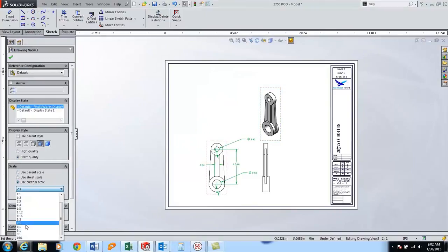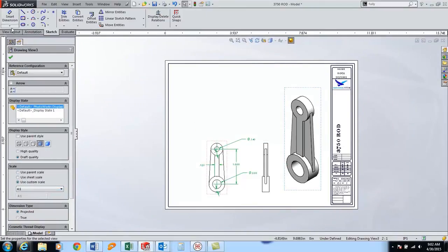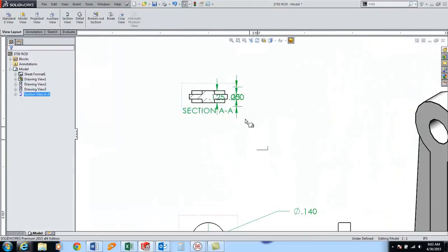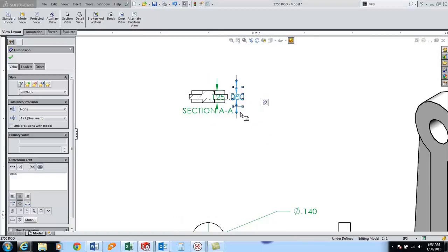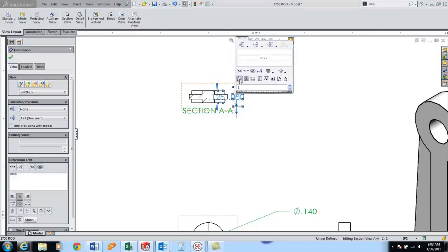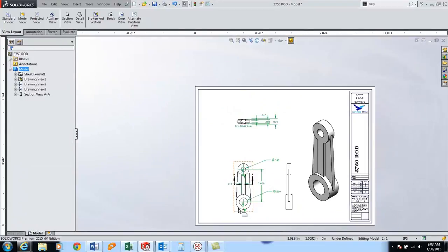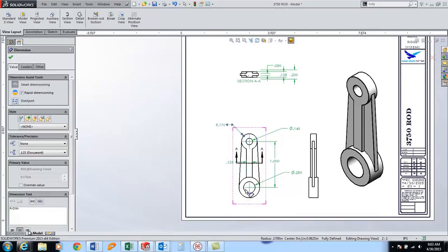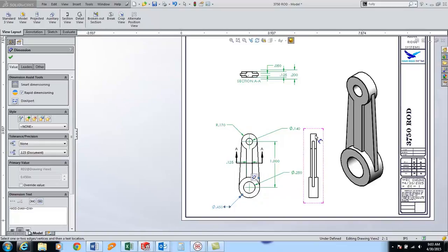To get this drawing finished, I can use shading or change the scale on any view. I can also create section views. Note the automatic cross-hatching and dimensions. They came in messy, but SOLIDWORKS has tools to give nicely spaced dimensions. Now I'll delete the offset dimensions and replace them with outer diameters. We can see how SOLIDWORKS can quickly place and space reference dimensions as well.